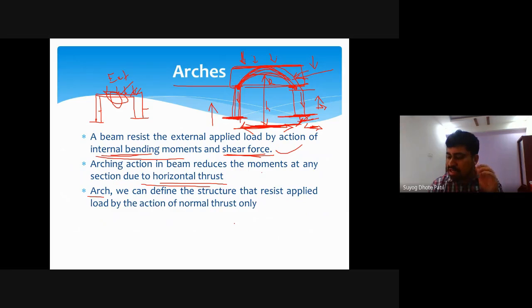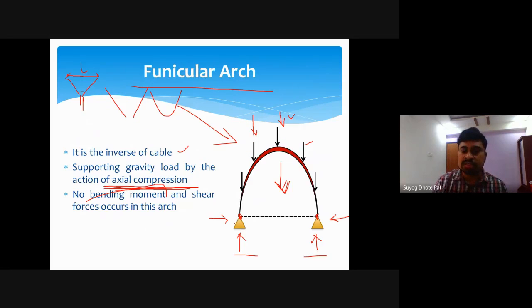Analyze means calculate the support reactions with regard to that horizontal beam. After calculation of these reactions, the number of unknown reactions or additional forces are calculated using horizontal thrust only, by the formulation of horizontal thrust in the case of arches.